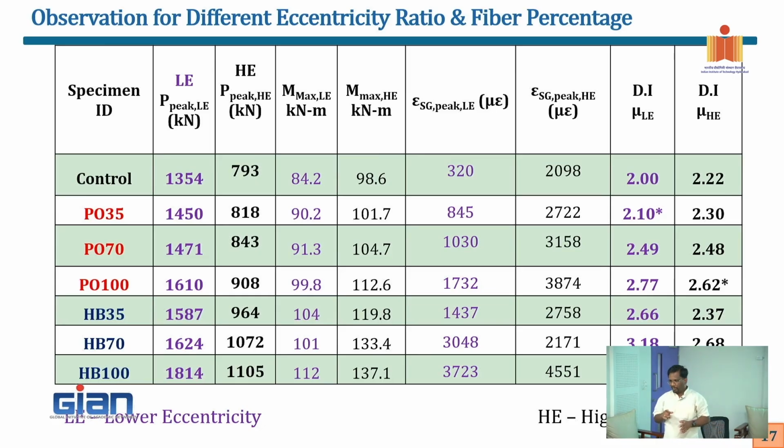Why we talk about ductility is that a lot of energy absorption goes into it. When the steel is yielding, it is going to dissipate a lot of energy. But here we don't have that. We absorb energy in a static sense, but we don't really dissipate the energy per se, just because we don't have the yield region. Yeah, that's the problem, right?